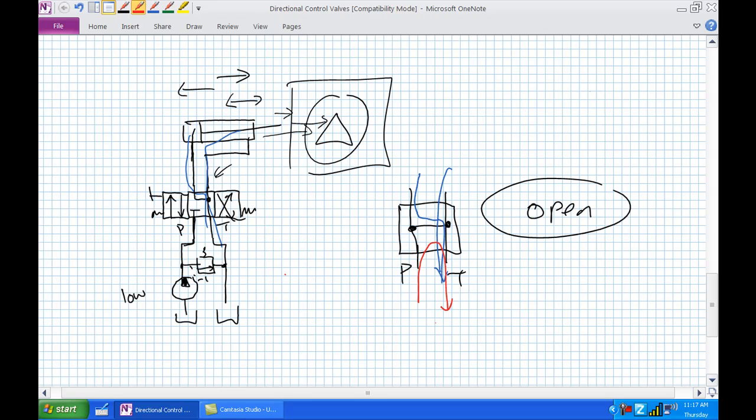And now what's the disadvantages? Well, you would never use this for a suspended load. A suspended load, you probably want to use a closed or tandem center position, okay? Because an open or a float would drop that load, okay? Just think about it. Now here is, well, let's go ahead and do this.